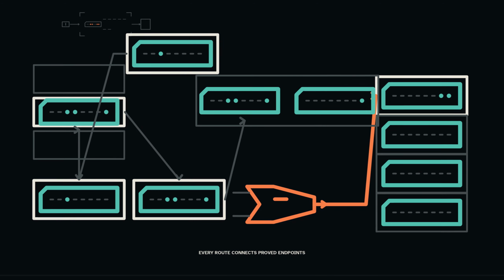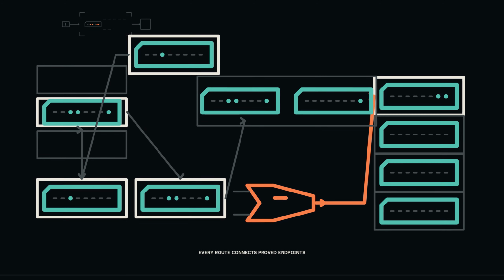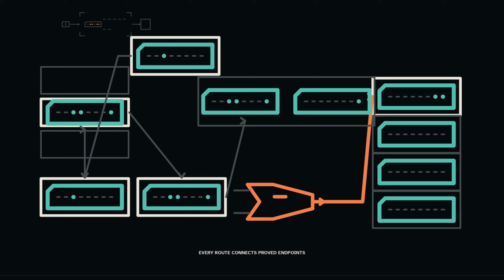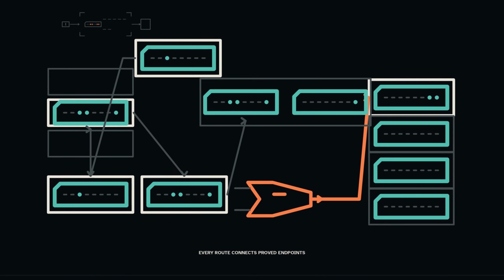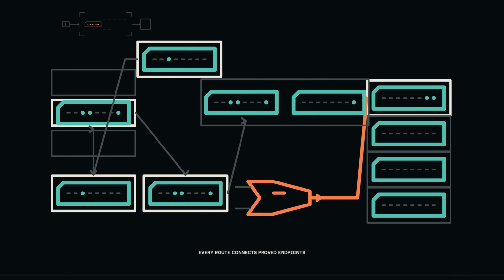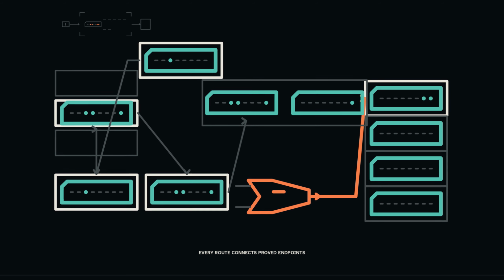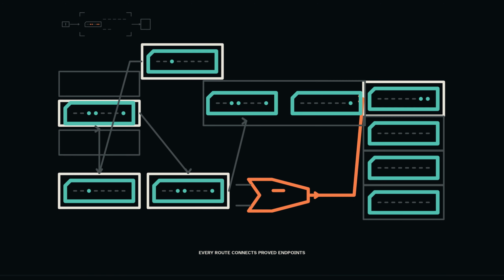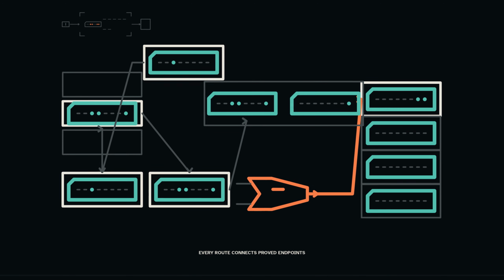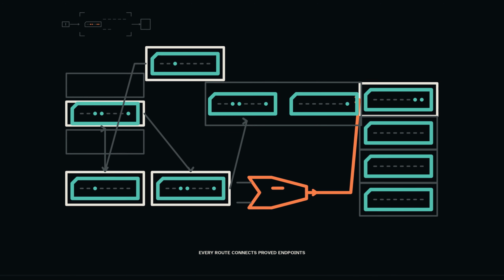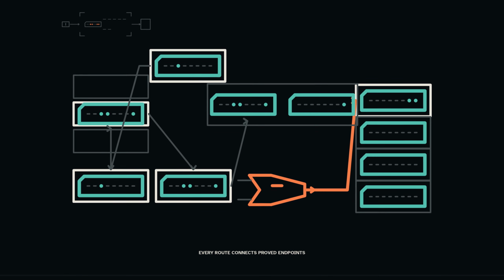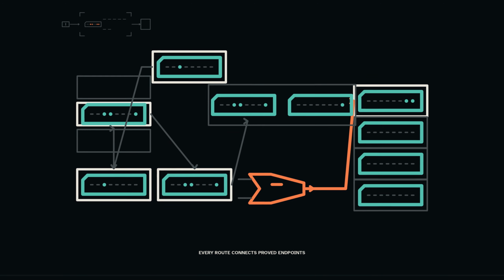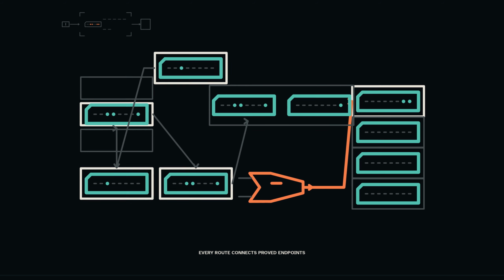3 different kinds of location now meet. The program counter holds the address of the next instruction byte to fetch. The memory address register holds the address currently presented to memory. The 2 instruction registers hold the 2 bytes just fetched. Those jobs must not blur together. The program counter tells the machine where the instruction stream continues. The memory address register selects one location for the current transaction. The instruction registers preserve the selected operation and operand while the controller carries it out.